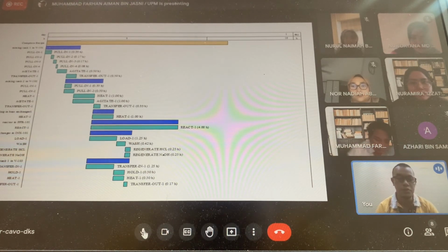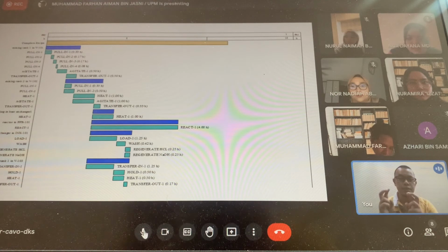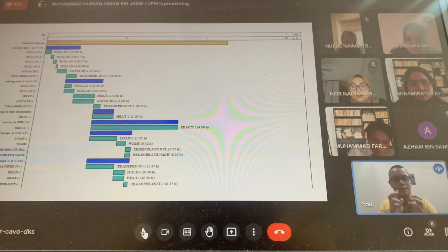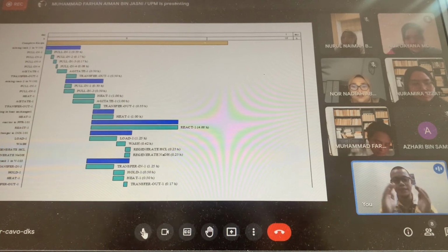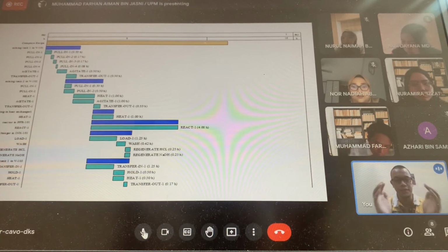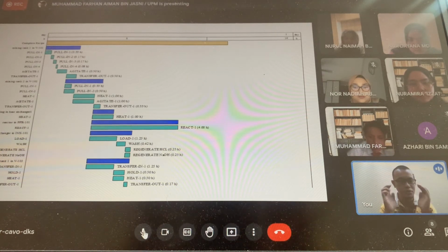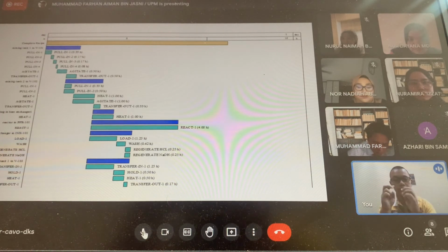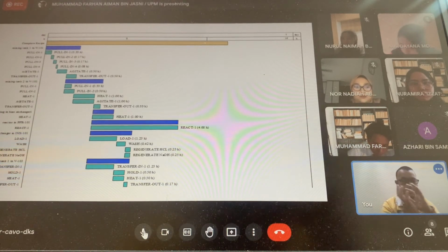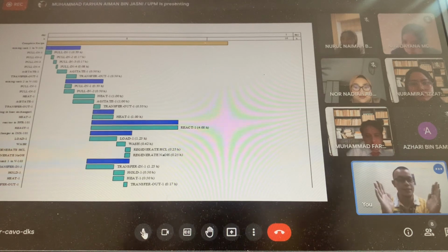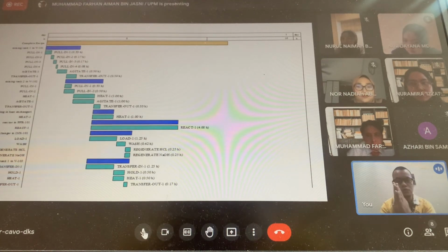So here you still have to put the sequence inside the reactor. You understand what I mean? In the reactor, you want to control the temperature at 40 degrees. The pressure is about 1.57 bar, isn't it? You want to control the temperature, and you want to control the pressure. So the sequence you have to put separately. Understand? Same goes for the mixture.